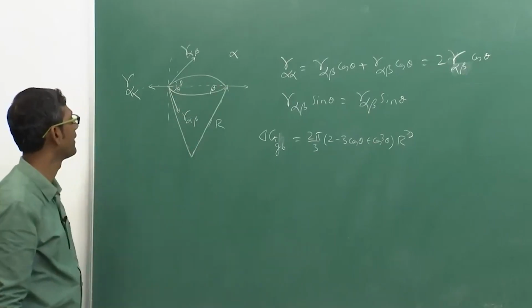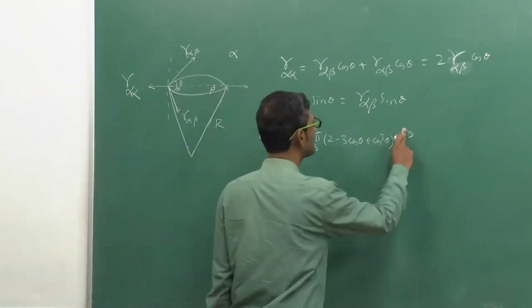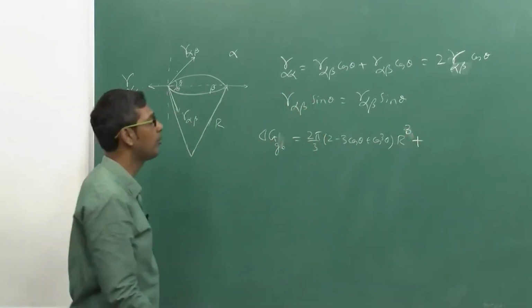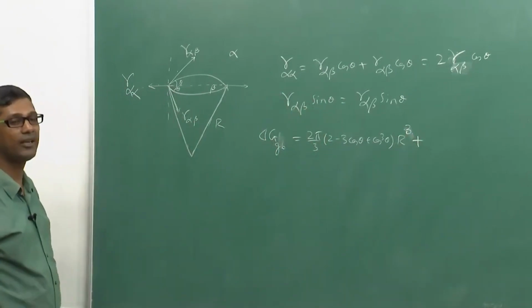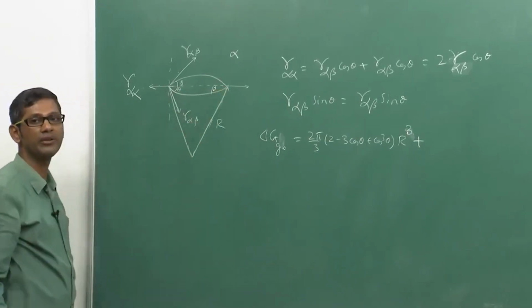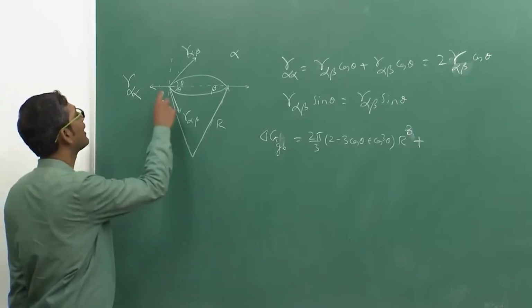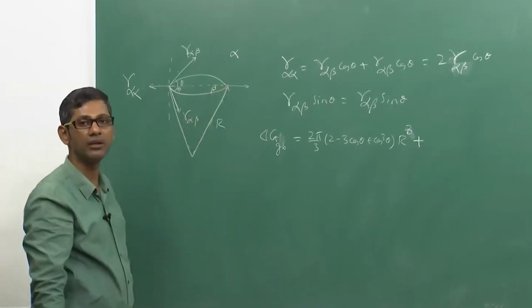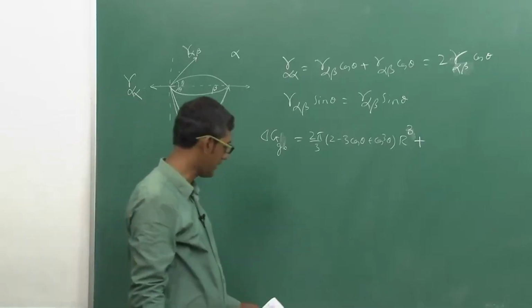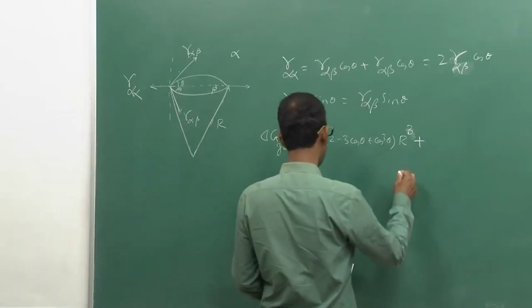Same way, I can draw a virtual sphere, correct. So now what is the loss of energy and what is the gain of energy? Obviously the loss of energy is these two interfaces created between alpha and beta, and the gain is that the earlier grain boundary between alpha alpha is now recovered. So let us write down that.